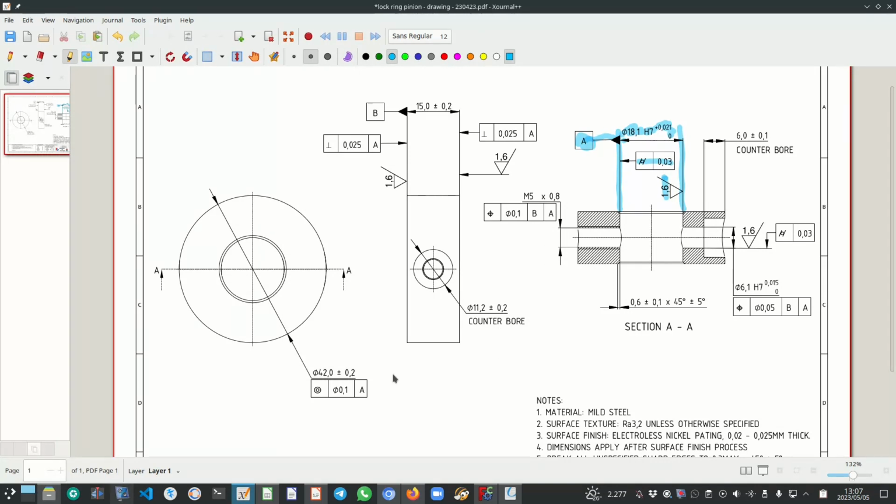Okay, so with that done, the next step is then, as I've said, to indicate the symmetry plane as datum B. How do I do that? I've got my extension lines here on this view. Okay, I give it the size, and here you can see the tolerance plus minus comma 2. It's not necessary for a tight tolerance.